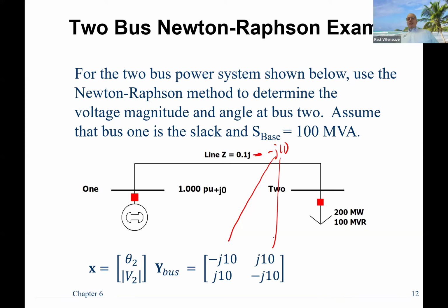You only have 2 buses, so you're done. And then you take the transpose of the matrix, so the rows become columns. And then the same thing, take the sum of the admittances connected to bus 2. So this is a pretty easy Y bus, right? It's only got one element to worry about. So that would be step 1 of what you would need to do normally.